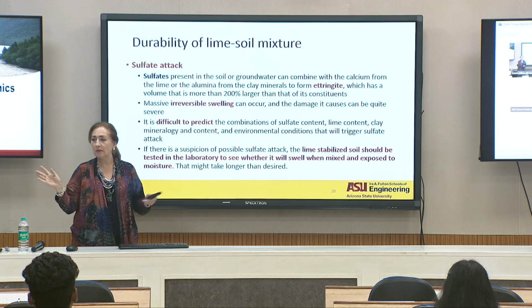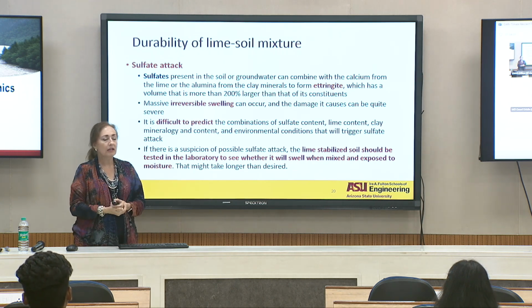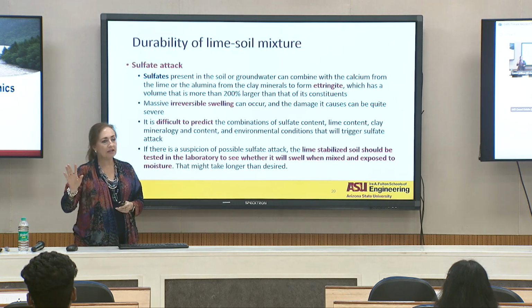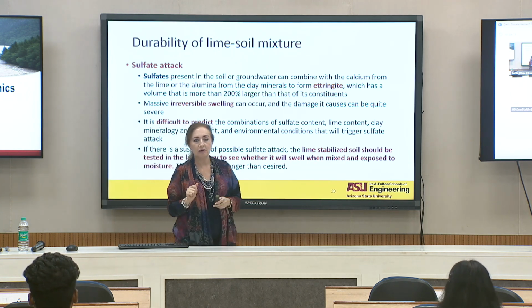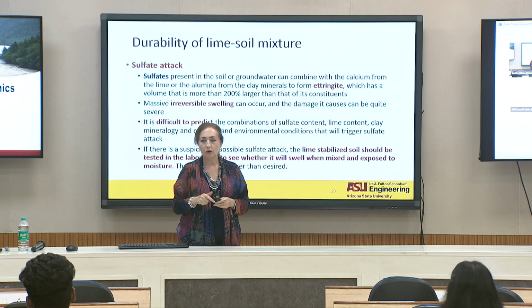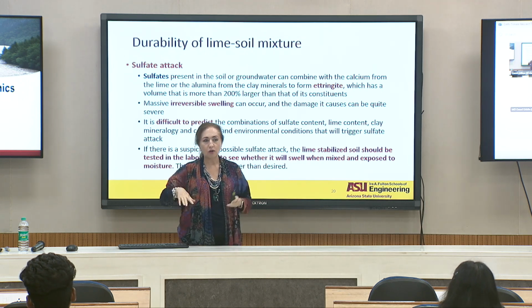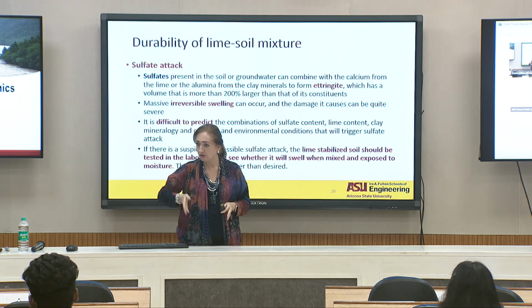Those were all on expansive soils, just street roads on expansive soils. They spent a lot of time and money to build them, and a year later, all of these roads were absolutely cracked. The soil was going up and down, with a lot of cracks all over the place, longitudinal cracks.